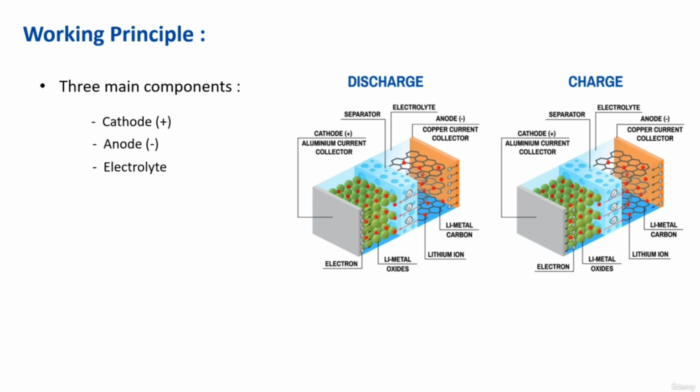electrodes. Taking lithium ion as an example, when the battery is charged, lithium ions are stored in the negative electrode, but they experience a driving force to migrate toward the positive electrode. The driving force for this is chemical, which means the lithium ions prefer to bond in the positive electrode material. The larger the bonding strength, the larger the potential in the electrode.